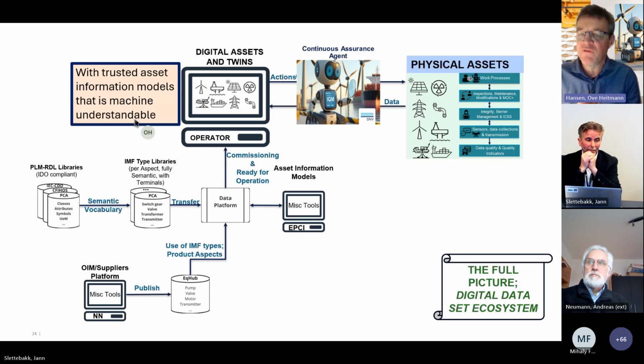And this is a very important part, because as we do a management of change process today, we normally have written in our procedures that if you do something like-for-like, if you change a pump with the same brand, with the same functionality, you don't need to do a risk assessment or an MOC process. We need to change that kind of procedure and behavior, because whatever you change in this pump will affect the asset information model or the digital representation.